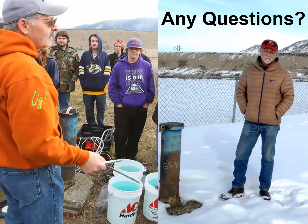And DEQ was actually given some money to give to the Bureau to drill a couple of additional wells. One of them was up by the Parrot, and they put in a well that would act as a pumping well. And when we drilled that well, some of us hydrogeologists were looking at it and going, well, down there, like 40, 50, 60 feet, it looks like really sand and gravel. And we thought, well, that's not 3 feet per day material, that's hundreds of feet per day material.